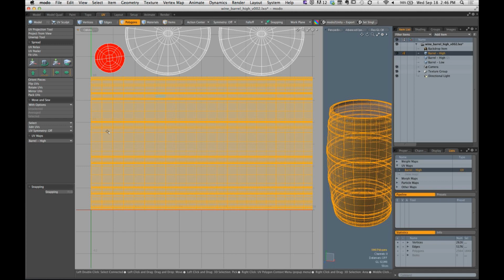Okay? You can double click on them. That's fine. Double click on it for me. Or, I'm sorry, double click on the edge on the mesh itself. There you go. Now, hold down your control key and just drag out a box around the one below. That's going to deselect it. Remember, holding down control will deselect those edges.